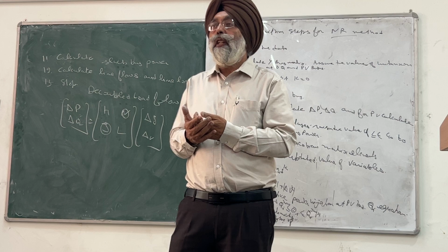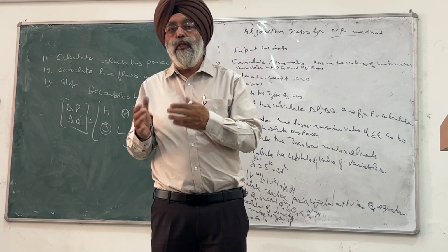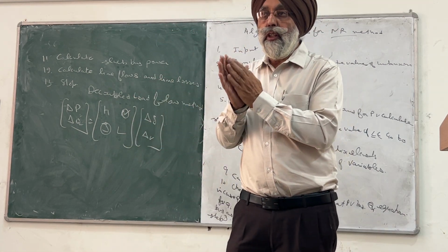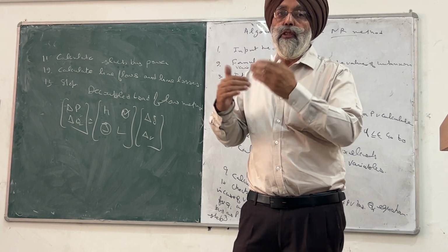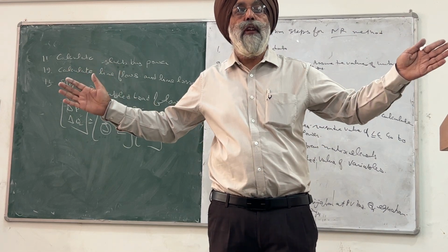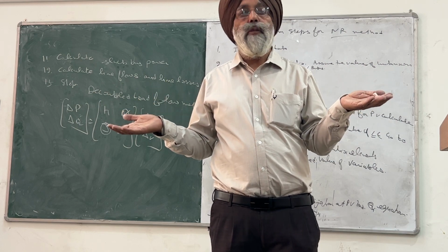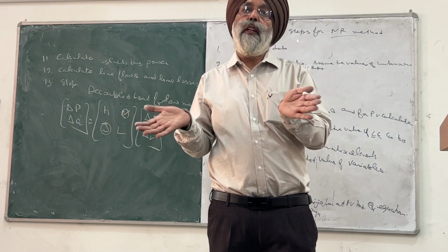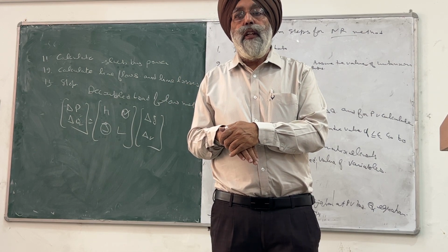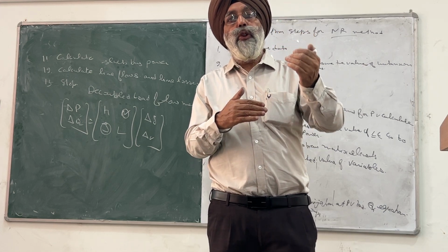Sometimes in the examination you are asked to state the differences. In case of the Raphson method the per iteration burden is more, but the number of iterations does not increase much with the increase in buses. When the system grows and we have a large number of buses, say 1,000 buses, then the Gauss-Seidel method sometimes fails, or it is not giving accurate results, and as the number of buses increases, it starts taking more and more time.